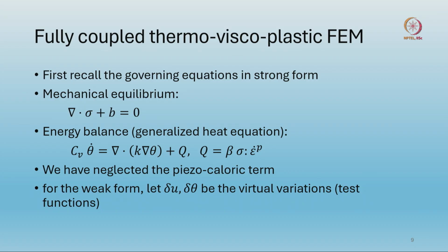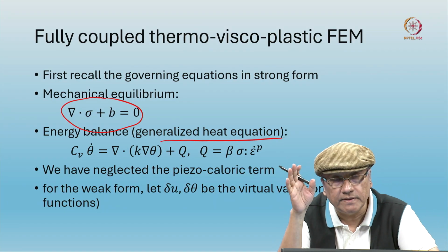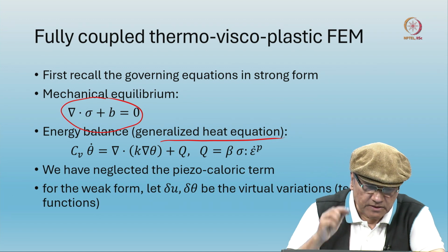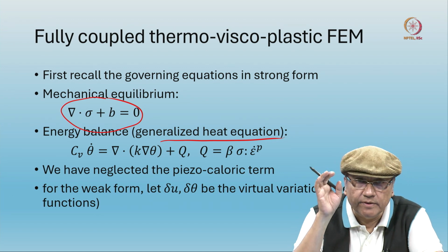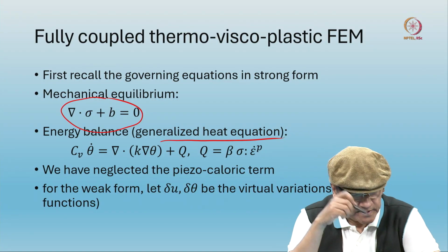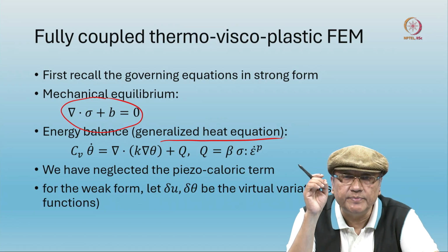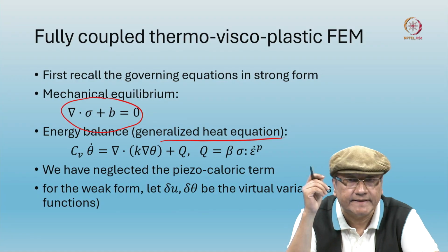So, first we have to start with the governing equations, all right. There are 2 governing equations of interest here. One is the mechanical equilibrium, which is here, and the other is the generalized heat equation, which is the PDE, partial differential equation, in the temperature theta. In this we have ignored the piezocaloric term. Typically I told you, when we had the discussion on this generalized heat equation, that the piezocaloric effect is often neglected.